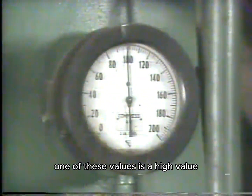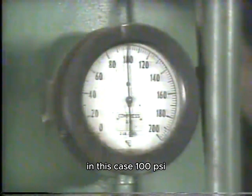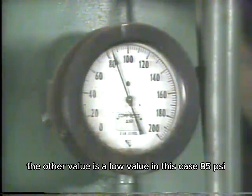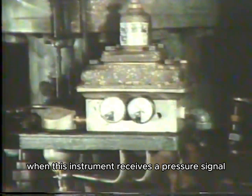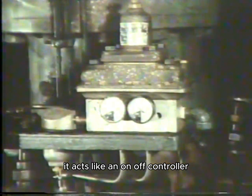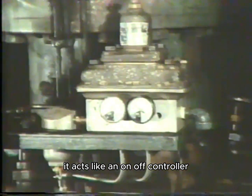One of these values is a high value, in this case 100 psi. The other value is a low value, in this case 85 psi. When this instrument receives a pressure signal below 85 psi or above 100 psi, it acts like an on-off controller.